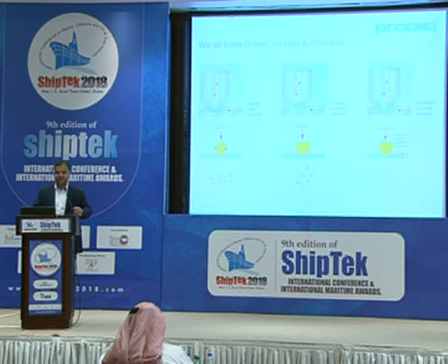The first one is the Brinell. It has a ball indenter. It exerts a fixed force. There is an indentation. We measure the indentation depth and the area and calculate the hardness value. The other most common hardness scale is the Vickers. It has a pyramid diamond, and basically again it's the same indentation method. And the Rockwell, again it has a 120 degree conical diamond, basically with a fixed force. The indentation is done, and then we measure the indentation depth from the peak load to the preload. This is how the hardness value is calculated.